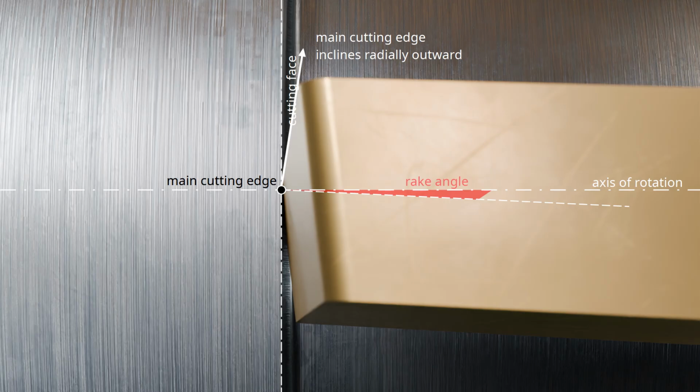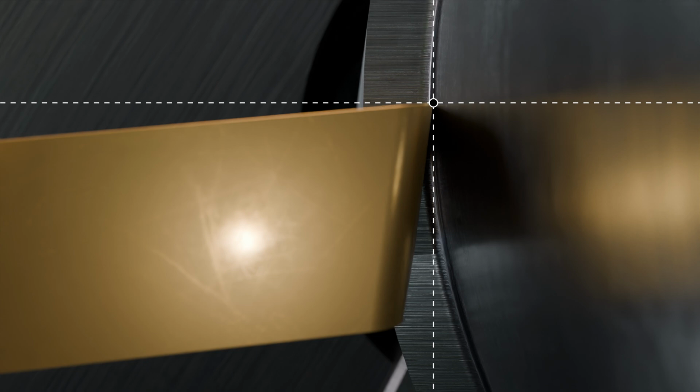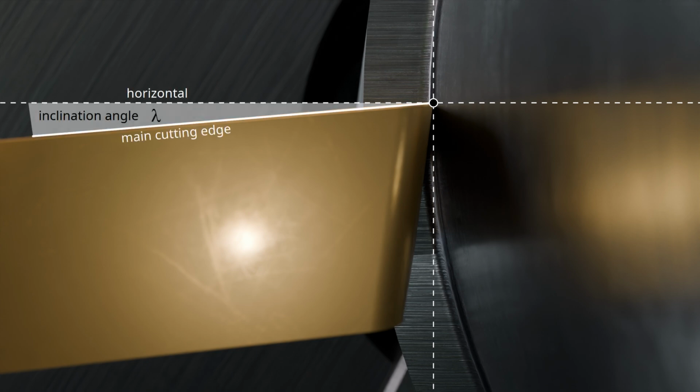Both the radial and axial inclinations ultimately determine the position of the rake face and thus influence chip formation. To define this radial inclination angle, we need to look at the indexable insert in the axial direction. The inclination angle lambda is then the angle measured in the radial direction between the main cutting edge and the horizontal.